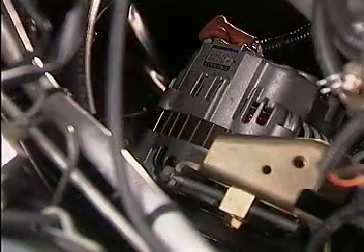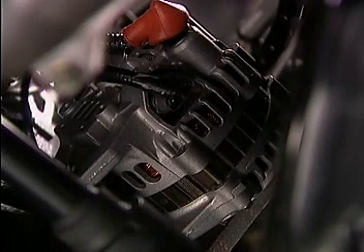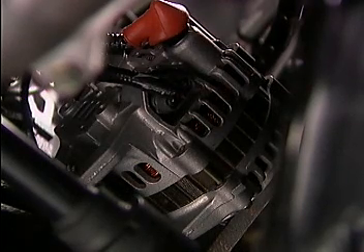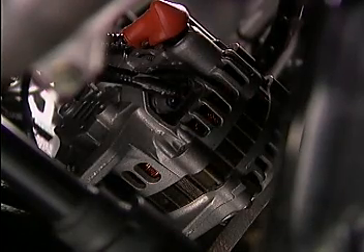Both engines use a new generator for 1997 with a low noise fan that reduces interior and exterior noise. The ECM controls the generator output and resulting load on the engine to minimize quick changes in load at idle as electrical accessories are used. This results in lower exhaust emissions at idle. You've seen this type of generator on the Galant and Eclipse.